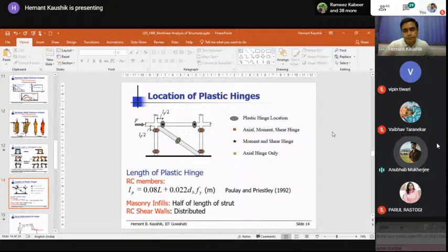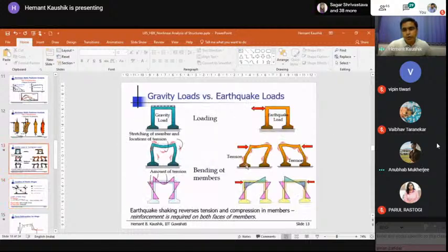So at that location, the bending moment is not critical. The bending moment alone is not important here, but rotation is also important. See, what is the rotation right above this joint? There is no rotation. The rotation actually starts slightly above that. Because of that fixity, the maximum bending moment, though it appears here, is so rigid that we don't have to worry about it here. We can consider slightly above that. And how much is that slightly is governed by this equation.